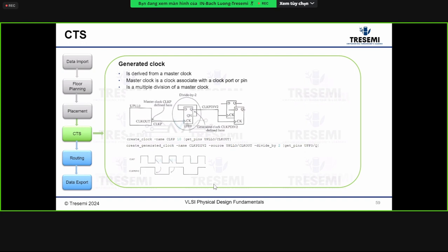Yeah, that was covered in the last session. Remember the stop pin: it's going to stop automatically if it's the source of another clock, which is this one, right? If you don't define it here, this is automatically recognized as a non-stop pin for the ICG cell, plus the generated clock.